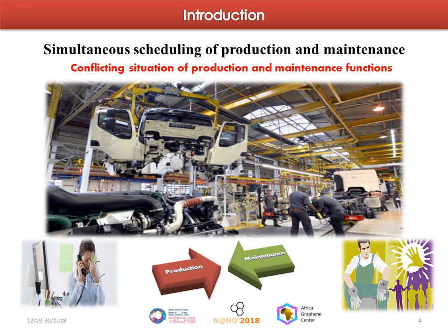This presentation addresses the problem of finding a robust and stable schedule for a single machine with availability constraint, in order to optimize the multi-objective of the system: the total energy consumption, the robustness, and the stability. The machine suffers an unexpected breakdown and follows a Weibull failure function. A model for integrating a time-based preventive maintenance (PM) and the production schedule is proposed, in which the sequence of jobs, the PM time, and the planned completion time of jobs are determined simultaneously.